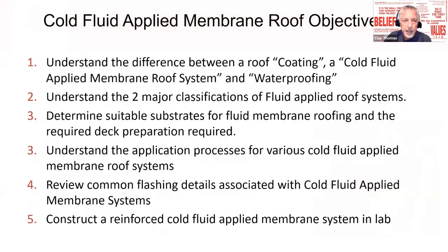So the objectives for today: we want to understand the difference between a coating, which we talked about last week, again, which is mainly to extend the life of a roof system, a fluid applied membrane roof system, and waterproofing. Understand the two major classifications of fluid applied roof systems, determine suitable substrates for fluid applied membrane and roofing deck preparation required, understand the application processes for various cold fluid applied roofing membrane systems. We're going to review the common flashing details associated with them and reinforce cold fluid membrane systems in the lab.